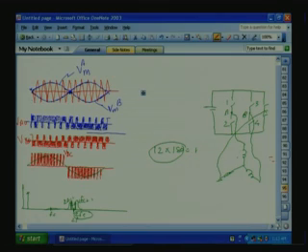This is our N, which will not be connected here. All the switching depends on the pole voltages A, B, C; we are concentrating on the pole voltages. Triple-N harmonics are suppressed because the neutral is not there.